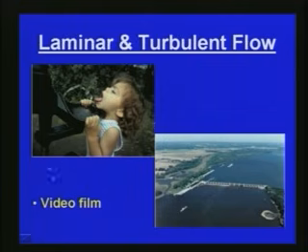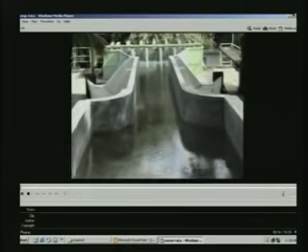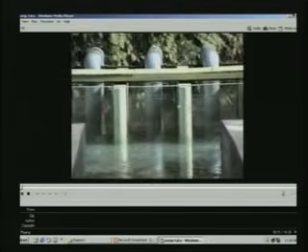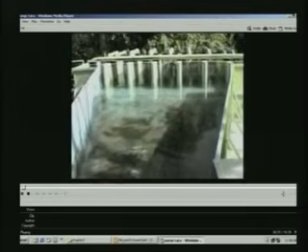Again, we will see how the flow can be laminar or turbulent in an experiment which we conducted in our hydraulics lab. Here you can see one of the experiments which we did in our hydraulics lab, where a sump pump test is done. Here you can see an open channel where the flow is initially laminar, and then there are some pumps, and due to the pumping effect the flow velocity or discharge varies and the velocity increases. Then you can see that the laminar flow at some part of the channel becomes turbulent. The flow becomes very disturbed, and the laminar flow is transformed into turbulent flow.